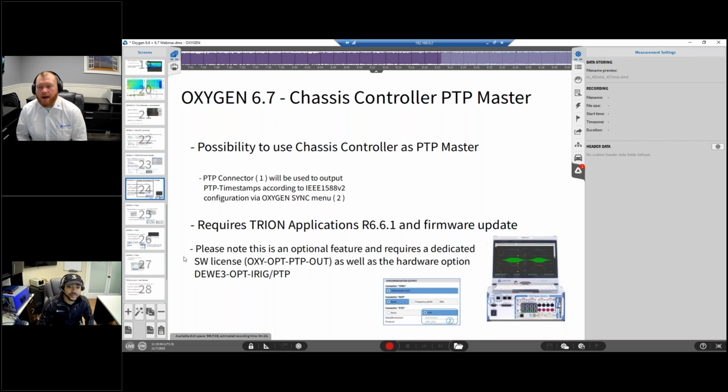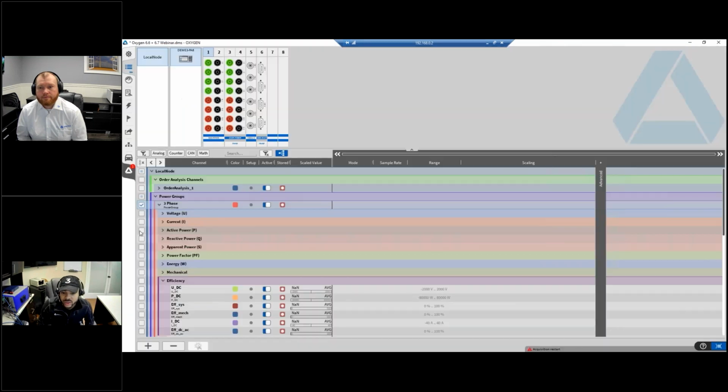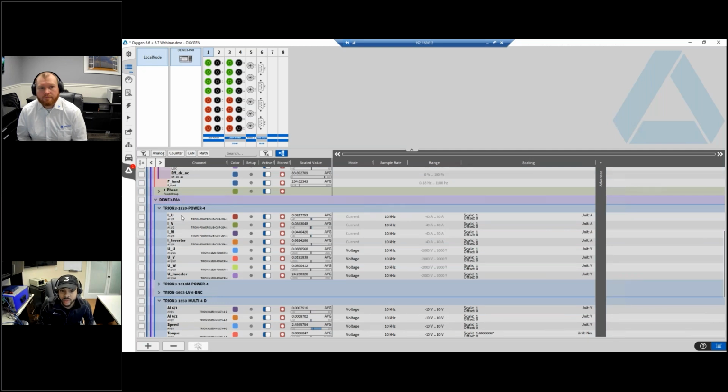Okay, understood. So we just have a couple last updates to the Oxygen 6.7. Just some improvements with naming the channels and being able to duplicate channels. And if you did make a mistake, now that shows up on the screen. So if you'd like to explain a little bit more on that. Yeah, so if you needed to go back to the default name, or there were too many channels to keep track of, you would just highlight the channel name, hit backspace, hit enter, and it would change right back to default.